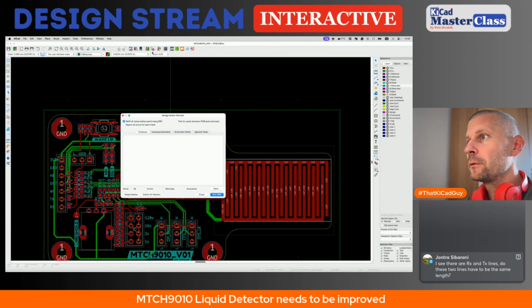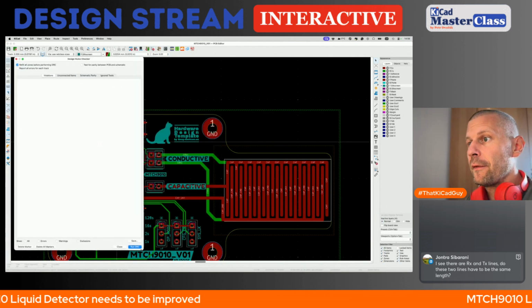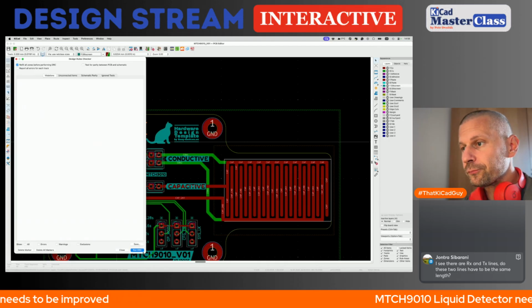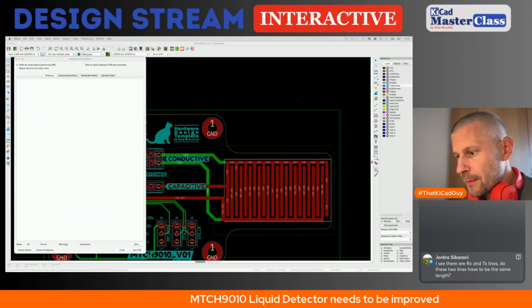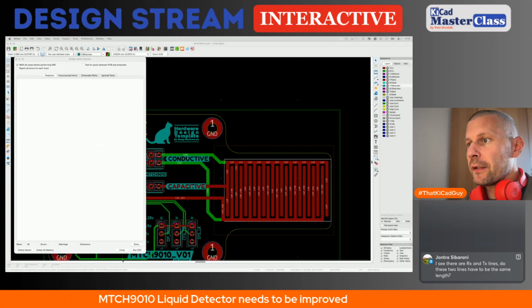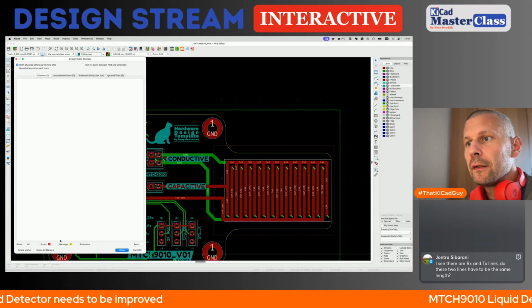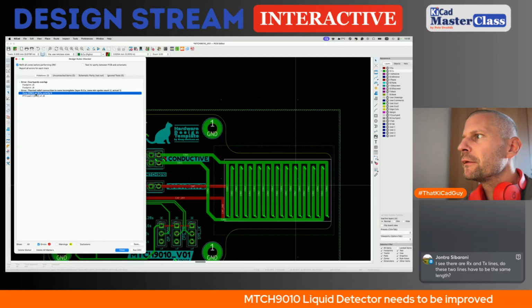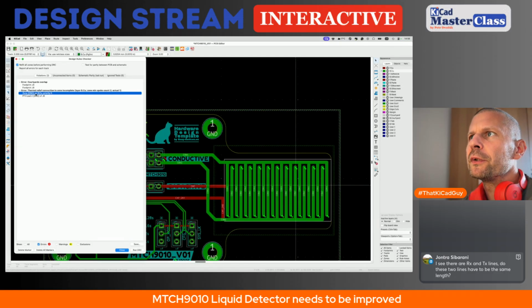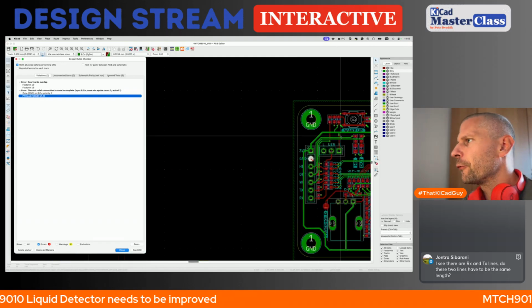Okay, it's time to run the ERC, or DRC, pardon, DRC. DRC is here, and let's call it, no blinking. Yes, thermal zone incomplete for this one.